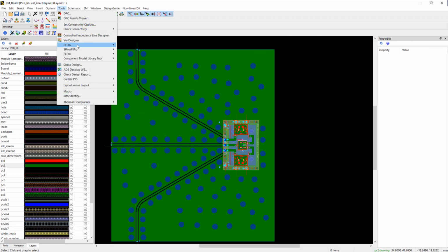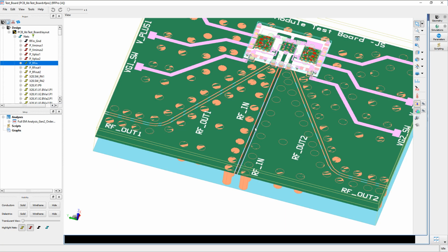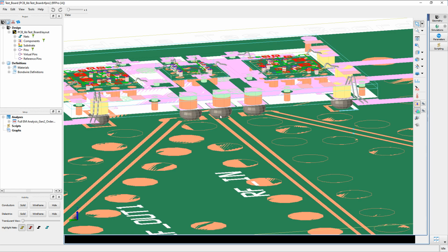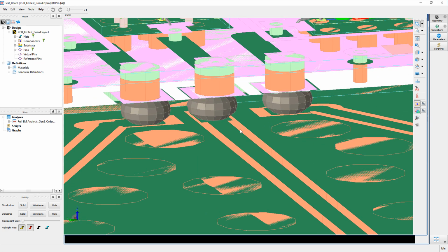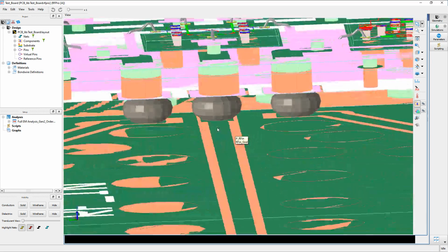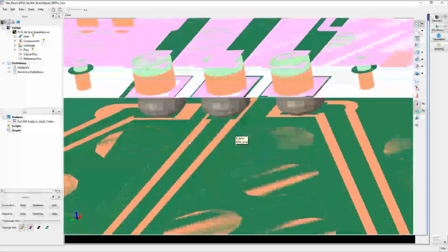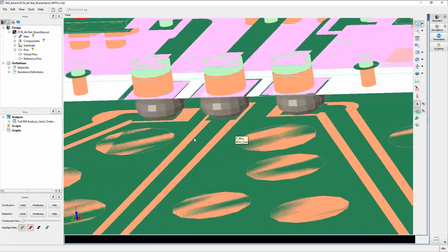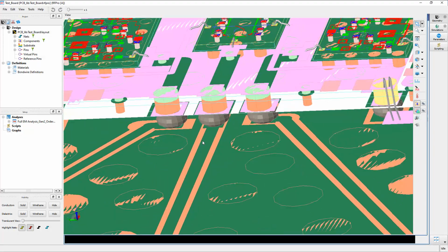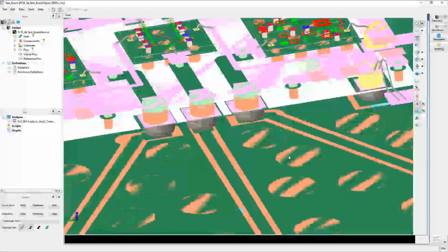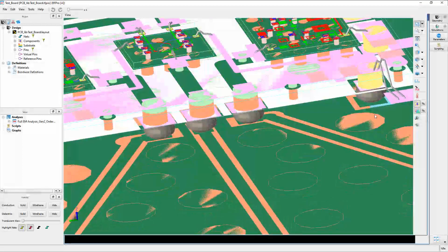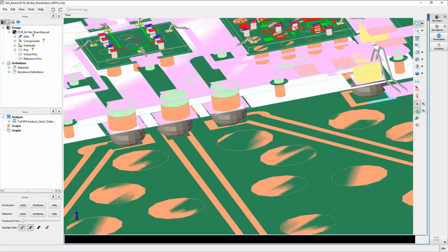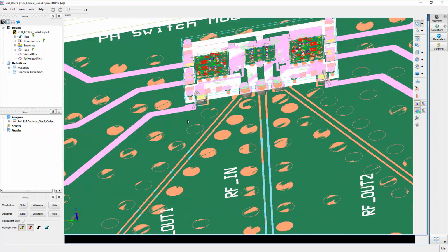So I open RF Pro just like we did before, and I analyze now the whole board. And truly, this is the beauty of this integrated 3D EM co-simulation environment. Everything is automatically imported from layout to the RF Pro page. You do not touch the layout. You run the EM simulation with automatic circuit models co-simulation, and if you wish, you can add virtual pins on the RF Pro page and do customized user-defined analysis. It's very flexible and automated.